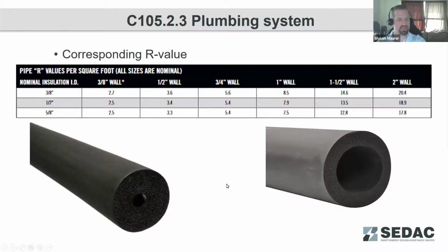These refrigerant lines, typically the cold line is well insulated, well protected, but the hot liquid line is exposed. Where this is inside the building, this will dump a little bit of heat back into the building. On the outside of the building, it leaves that pipe exposed to corrosion, weather effects. So again, that line does need to be insulated, both the hot liquid line and the cold suction line. It's important for the overall performance and efficiency of the HVAC system.